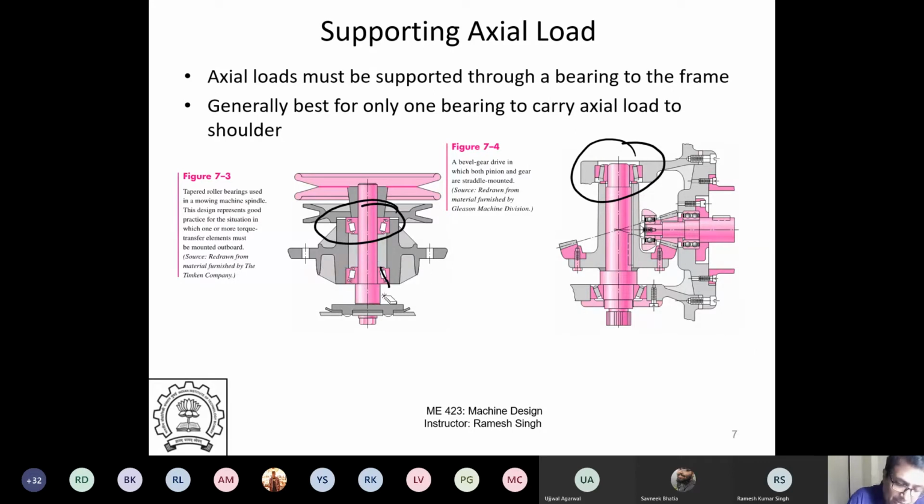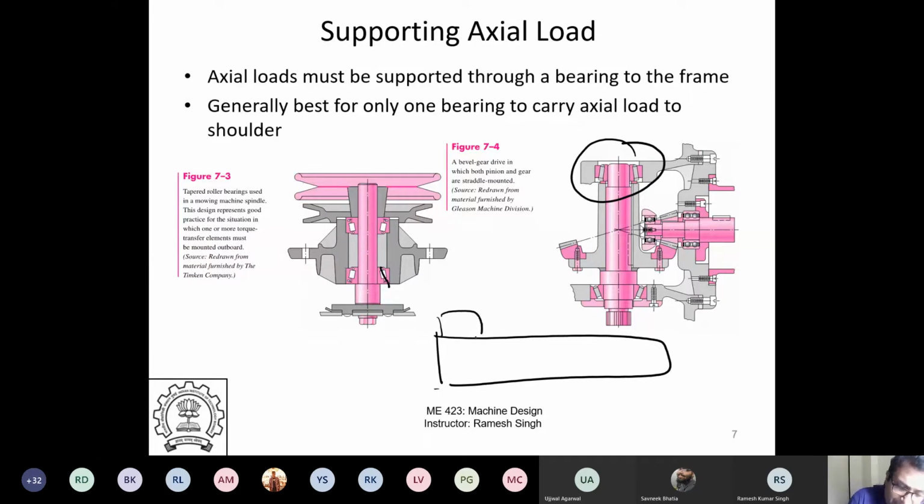So imagine I have a shaft. I have bearings here, right? These are just plain ball bearings, right? So what happens is if I have just say radial loading and I have reactions here, this bearing will work because there is only radial loading. All the loading is normal to the shaft.